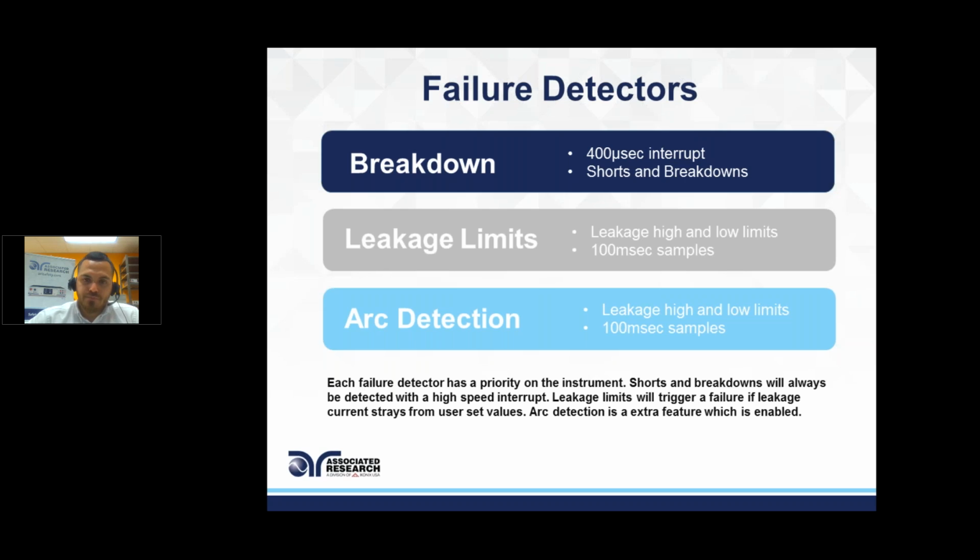A breakdown. As I stated earlier, a breakdown is a complete breakthrough of current through your insulation. This is a quality issue. This is potentially a design issue. But in essence, I know that that insulation cannot protect. Well, maybe it can protect. Maybe, sure, you failed at 1,240 volts, but maybe at 500 volts it would have passed, at 1,000 volts it would have passed.